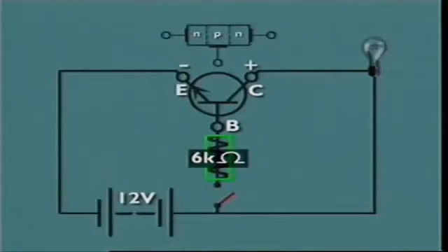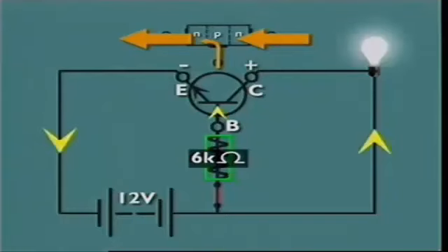In this circuit, this NPN transistor can act as a switch. If the control switch is open, the depletion layer at one PN junction is blocking current from flowing through the transistor and driving the load. With a closed control switch, a small current flows through the emitter base PN junction. The base has only a limited number of charge carriers, so extra ones flow across the emitter collector PN junction, letting current operate the load. The transistor then operates as a low-resistance conductor. A small current through the base lets larger current flow across the emitter collector junction. The transistor is then said to be turned on.